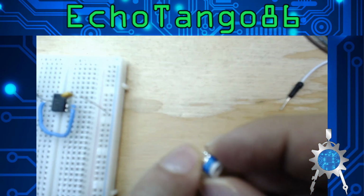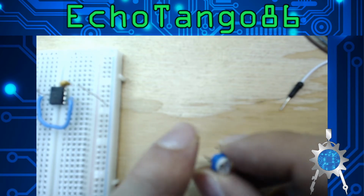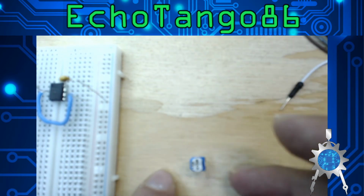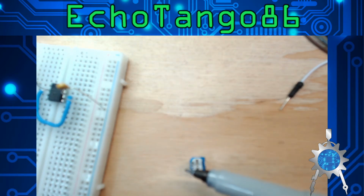I like to use the middle pin, the one by itself, as one end, and the side that's on the top in this orientation here. I don't know if it'll stay in that orientation. Sorry guys. So, in this orientation here we have the flat side. If that's facing my right, I call this the top, and then the middle, and then the bottom. So on the top we'll have it connect up to pin 7, and also our 1K resistor. And on this one we'll go into pin 6. And then the bottom one won't be connected at all.